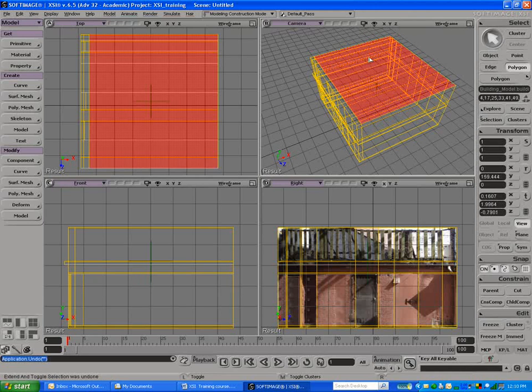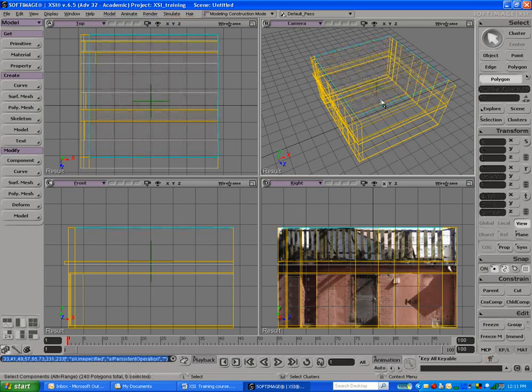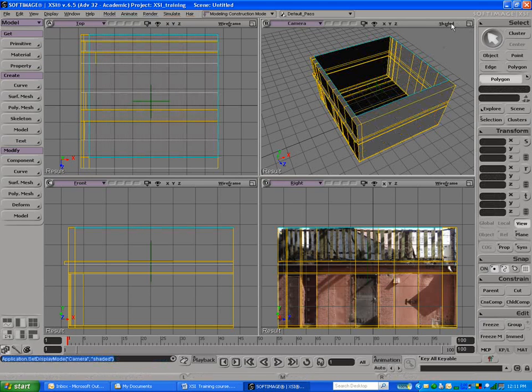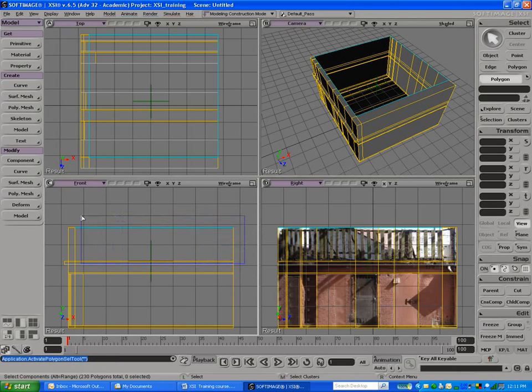Okay. So instead of extruding there, what we can do is we can actually go in. We already have everything we need in here, so I can actually get those faces selected, okay, delete them, and that's going to leave a hole. We can also get rid of these faces around here and delete those. In that case, the easiest way to get those is actually go in to a side view and hold Y down and draw a box around those.